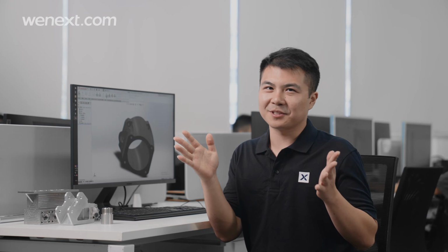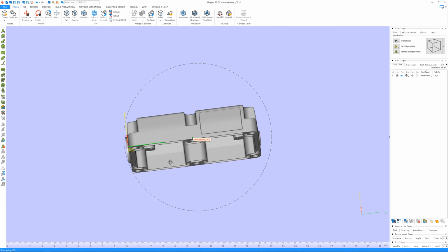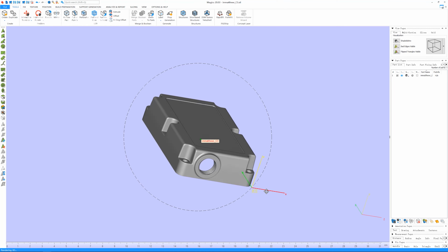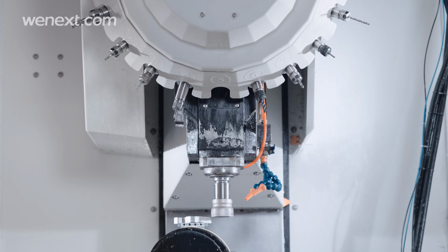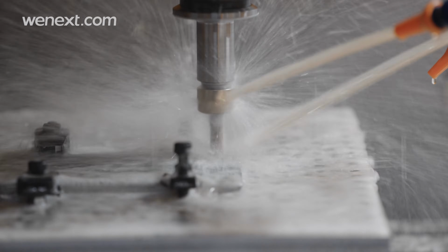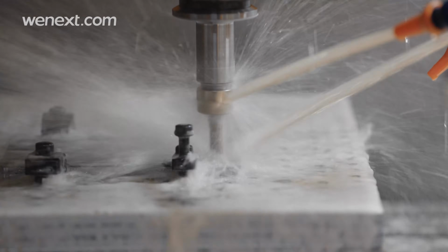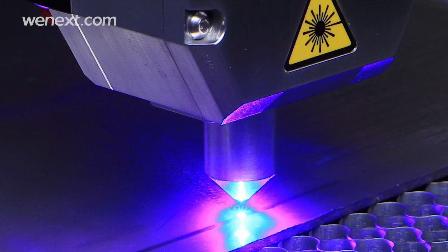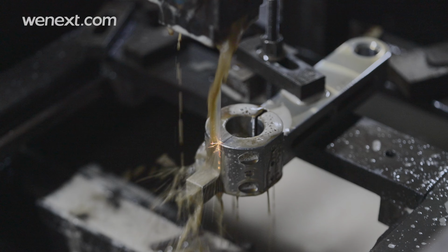Welcome to the second episode of Craving CNC. I'm Hemi. In the last video, we briefly talked about what exactly CNC machining is. Today, we are diving into more details. We have learned that CNC is a subtractive manufacturing technology that produces a part based on a CAD model. It removes material from a blank at high speed by cutting or spinning tools which are under computer's control. All of these natures make CNC distinguished from laser, plasma, and EDM cutting.